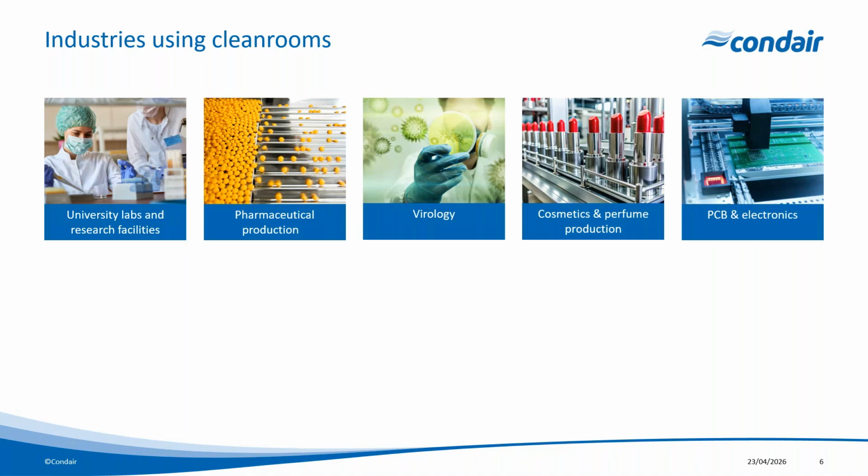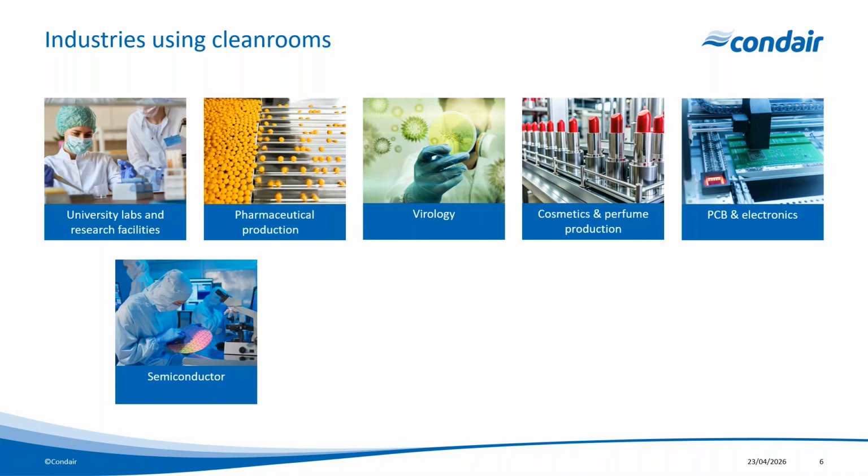PCB and electrics, again, the issue here is typically static that we're trying to reduce, and the static discharge can be quite significant. A very small static charge can be generated and actually unnoticed by us as we can't perceive some of the small charges that could damage a PCB or electronics. And again, we humidify to over 45% RH to enable any imbalance of electrons to distribute through the air to prevent static buildup. It's a more holistic approach than just local static prevention.